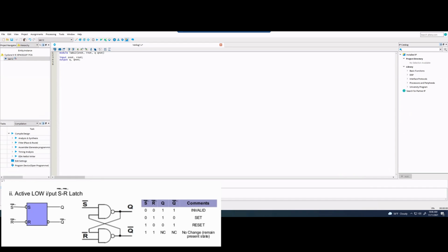So we're going to type in NAND, we need names for our gates. I'm going to call the top one Nand1 or Nand Gate 1. And then we need our output first. This outputs into the Q wire. So we're going to have Q. And the inputs are S0 and also R0. So we're going to close this and end this line.